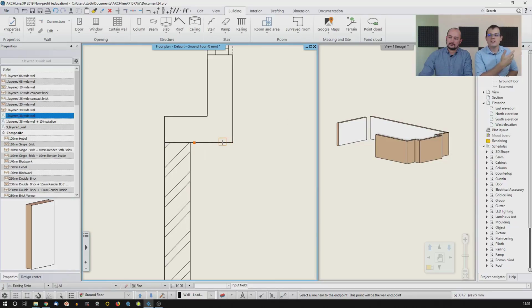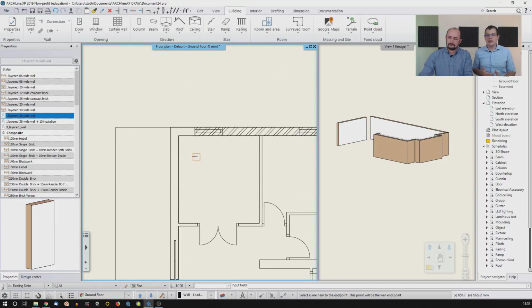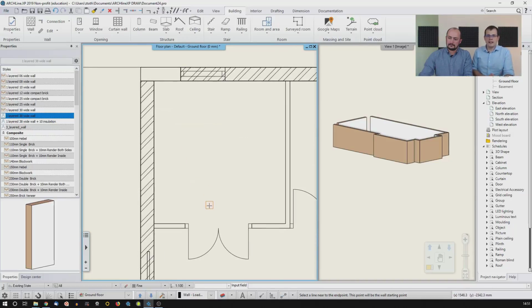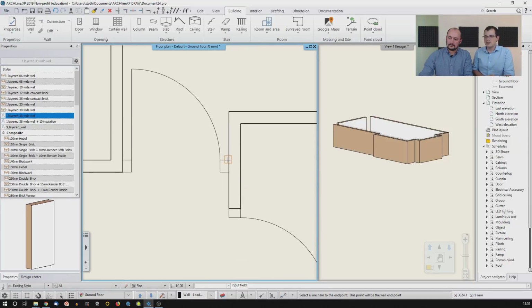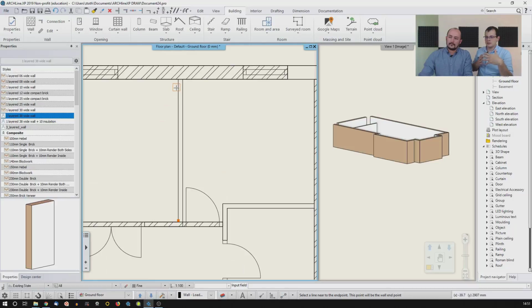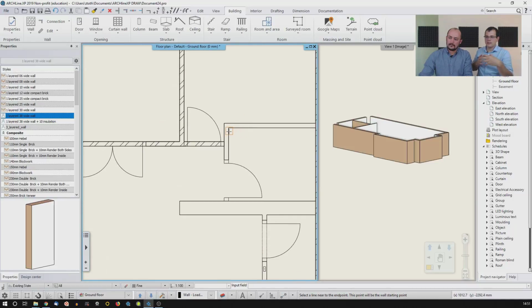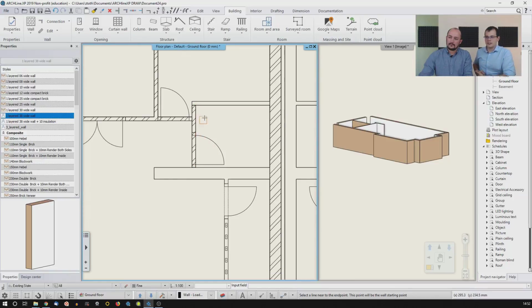But if this connection is not automatically resolved, if the T and L connection is not happening automatically, that's something you can manually override whenever you get there. And mainly for this reason, it's always worth going for a longer length. So when you have the chance to turn line work into wall, always start with the longer ones, because then the software finds it easier to turn this into an actual wall.